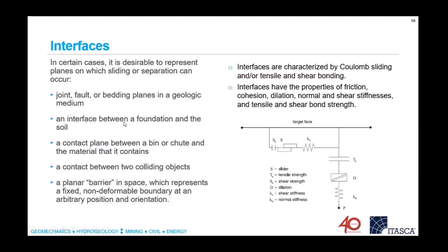For example, you can also separate a foundation from soil, or simulate how a foundation can move in soil. And basically all other applications wherever you feel like separation is needed, and there's some movement that can be along that interface. Interfaces are characterized by Coulomb sliding and tensile and/or shear bonding.